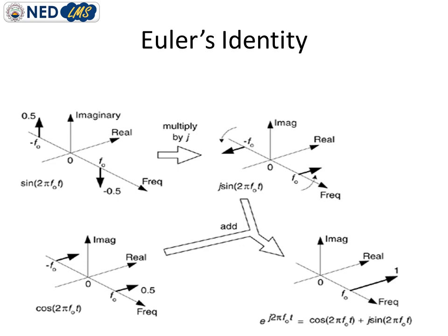But if you look at the positive side, we have the spectral line at f naught for sine plot as well as cosine plot. So these two spectral lines actually added up, and these spectral lines had the magnitude of 0.5 previously, and when they are added together, then the strength or amplitude becomes 1.